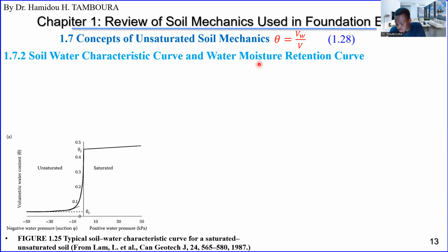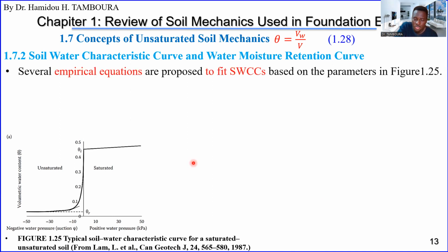Let's keep this formula here, and this figure also here. There are several empirical equations that are proposed to fit the SWCCs based on parameters in this figure here. This is a typical one. So I will just keep this typical one here. Our theta, the volumetric water content, is estimated using this formula, for example.